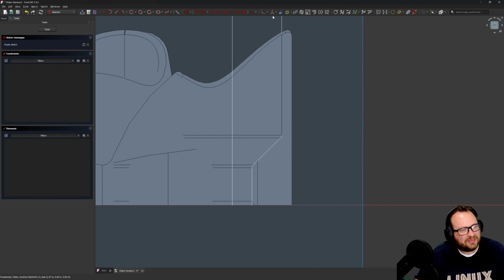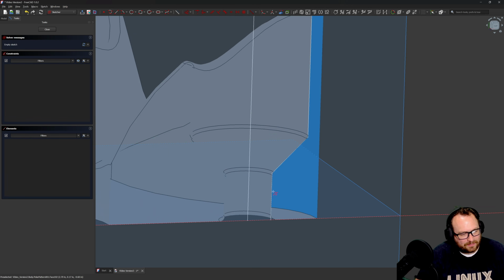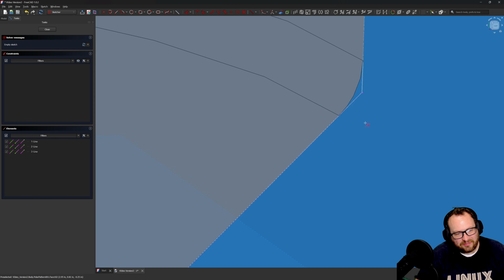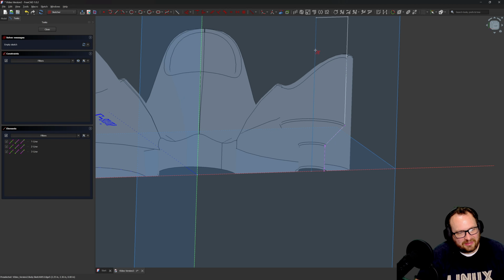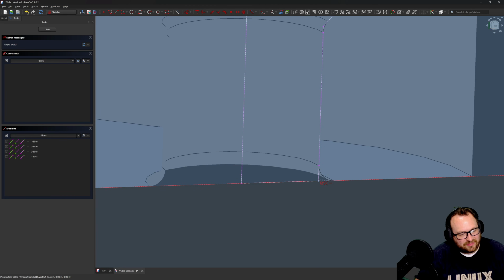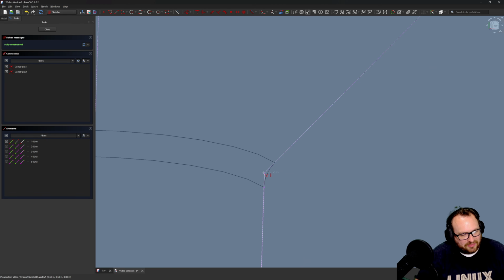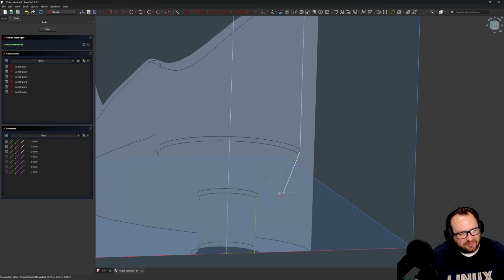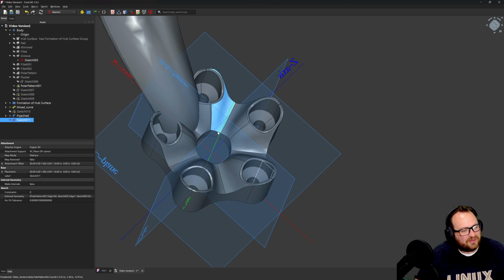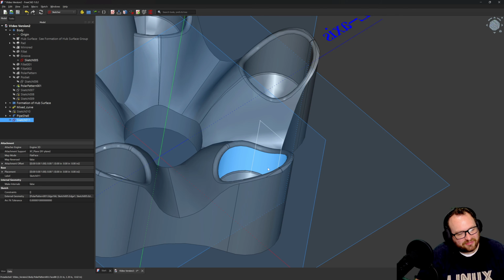It's perfect for what I need. We'll import some lines on this. There we go. We'll import that. We'll import that. And that. That should be enough. I'll select my multi-line here, and we can go from here to this point, from here to this point, to there, to there, and there. All I need to do now is add a horizontal there and a vertical there. And we've done it. So we have a fully defined sketch that sits right in there.